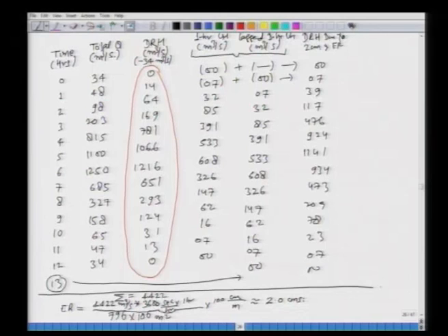All right. So, how do you find the unit hydrograph? Just divide this by n, and n is equal to 2. So, these ordinates you divide by 2, that will give you 2 hour unit hydrograph in meter cube per second. So if you did that, what I am doing is you just divide all these numbers by 2 and so on. So, you will have 0, it will be 4, do not worry about the rounding off. I am taking the whole numbers, 238,